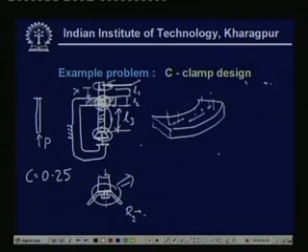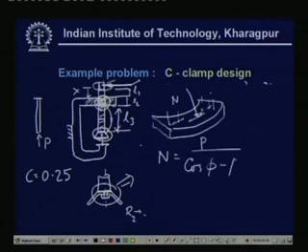If you remember from the last lecture, the normal force on it was P divided by (cosine phi minus mu times sin phi), where again phi is the helix angle. Now, for a normal thread, phi is very small. Therefore, this term is very small, and it is again multiplied by mu, which is again a small number.